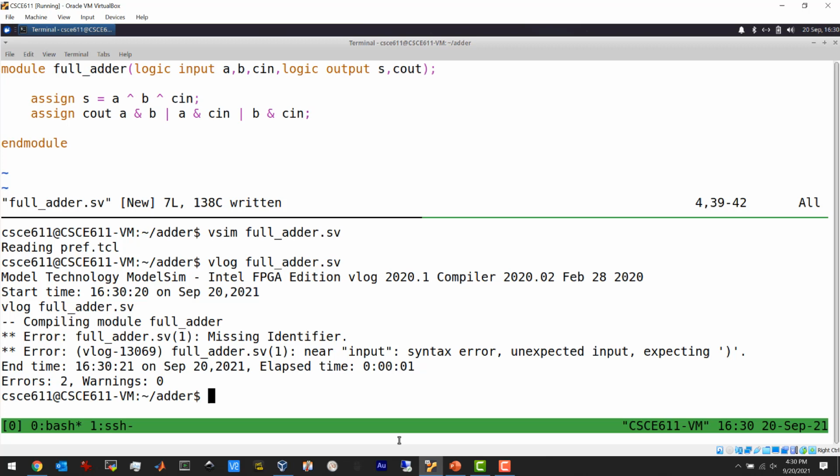But anyway, I just said vlog fulladder.sv, and I got an error on a line. Oh yeah, I forgot the equal sign. Okay, thank you. Yeah, and something about, oh, also I put, sorry. Okay, so a couple issues here. Number one, it should be input logic, not logic input.